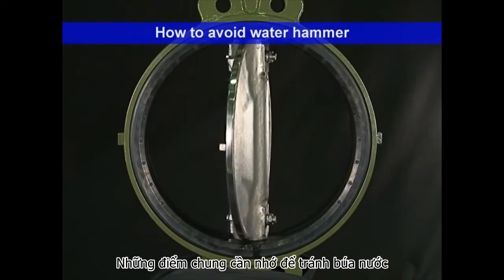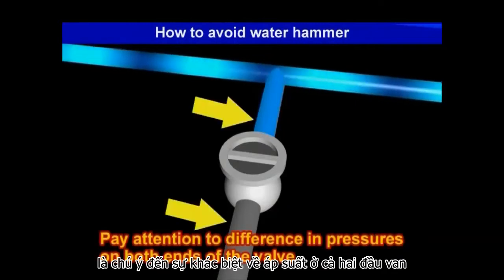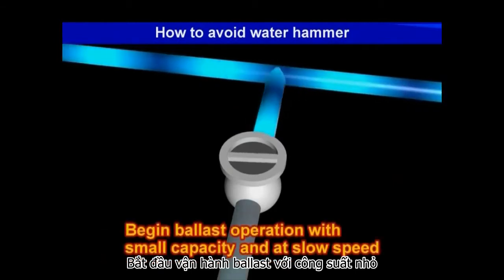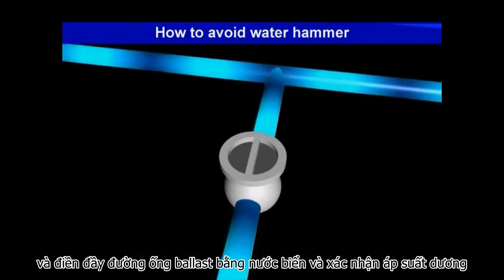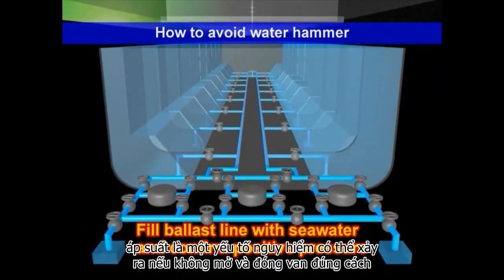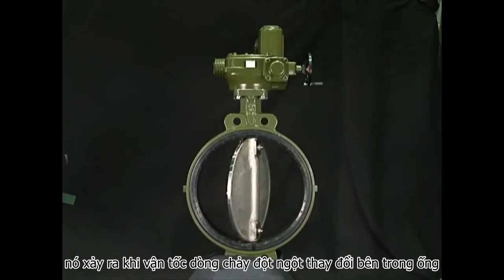In addition, general points to remember for avoiding water hammer are as follows. Pay attention to the difference in pressures in both ends of the valve. Begin ballast operation with a small capacity and at a slow speed. And fill the ballast line with seawater and confirm that the line has positive pressure. Pressure surge is a factor of possible danger with valve opening and closing.